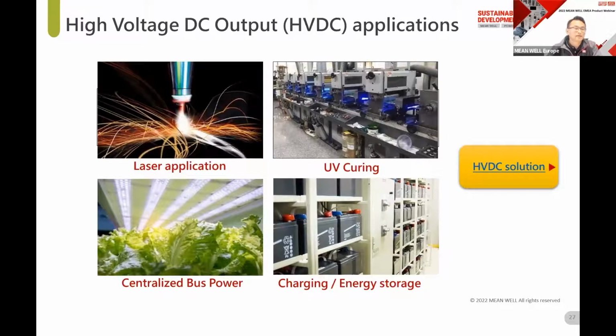High power with a high voltage has an advantage from the temperature concern because the high voltage runs with a low current. If high power is running with a low voltage, you can imagine the high current would bring up a high heat. It's more potential risk for those applications or systems.